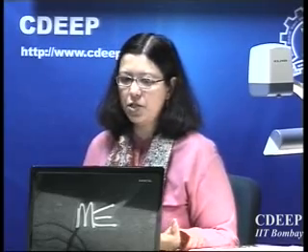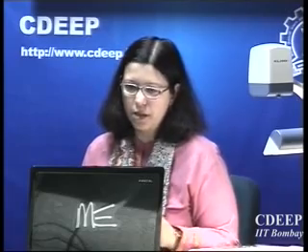So therefore, conversion time and sampling time are not the same. If you have a sampling rate, it may not be the rate your ADC can work with. That's why they are kept separate. One more very important thing is uncertainty in sampling time. Because sampling is done by the switch, finally what value is applied to the input of the ADC, and at what particular instant, is not perfectly known. That is called aperture error in sampling systems, and it is because of the switch.